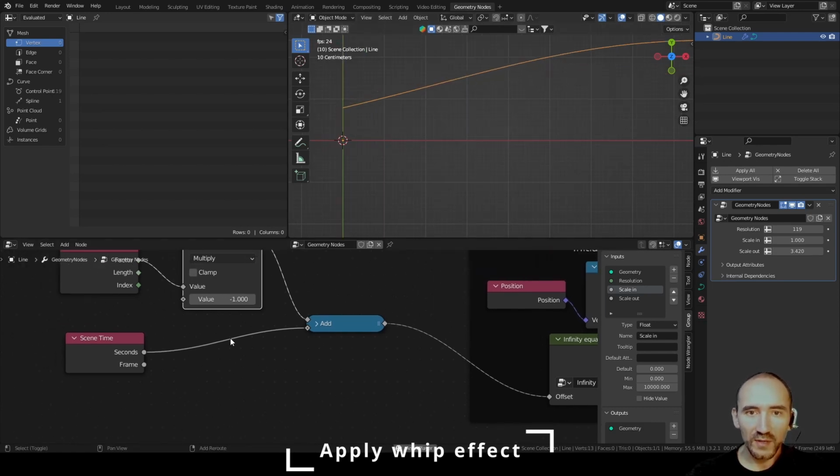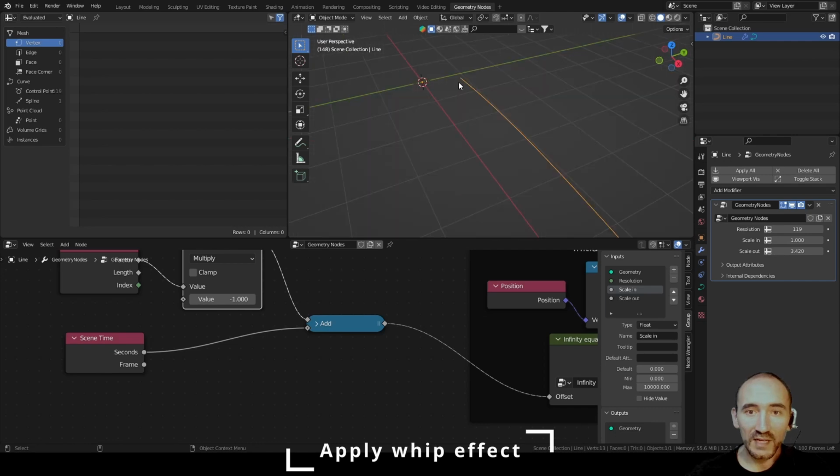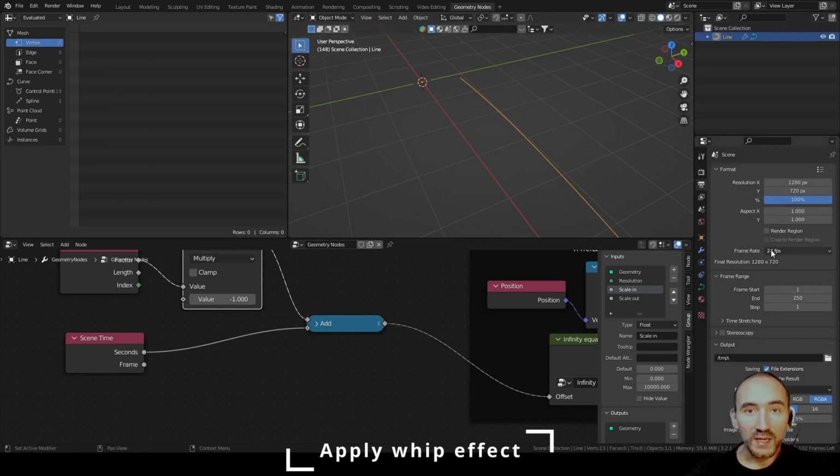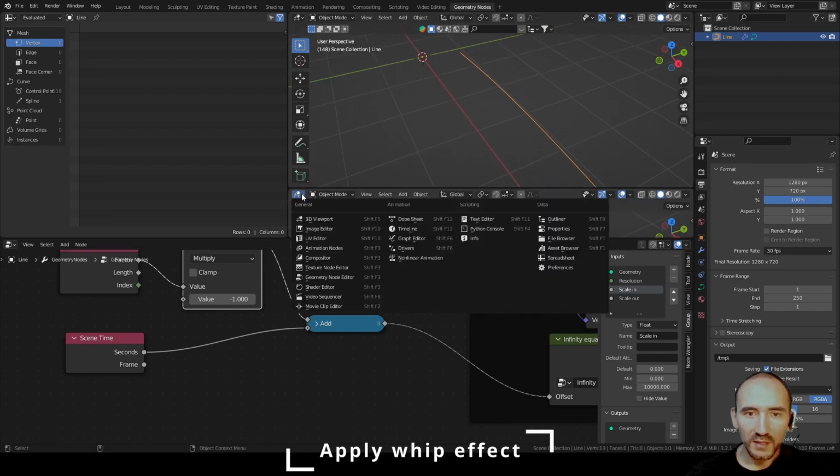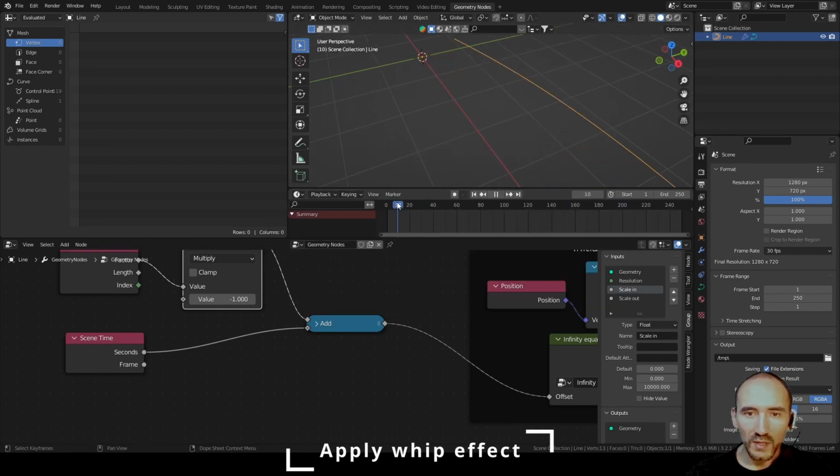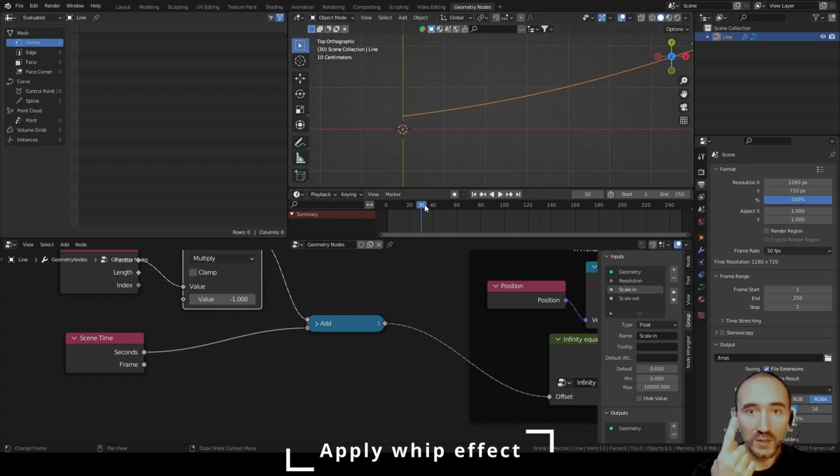So if I increase this, I have an entire round of the equation when I have the division of the frames by the frame rate equal to 2 multiplied by pi, as described before. So I increase this to 30, I add a little split here and choose timeline, so we can see at 0 I have 1, in 30 frames I have this value, so after 1 second, 1 round, and we will need this next.